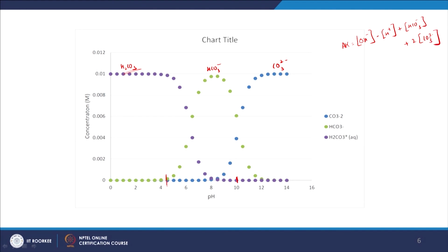Practically, what happens now? Let us say I am starting at pH 10 and I want to end up at 4.5. That means I need to add an acid, or titrate with an acid. I am starting from 10 and I keep adding acid. What is going to be consumed here? H plus is going to be consumed by HCO3 minus. Any H plus that you add is initially neutralized by HCO3 minus and transformed into H2CO3, and keep in mind that H2CO3 was our reference.